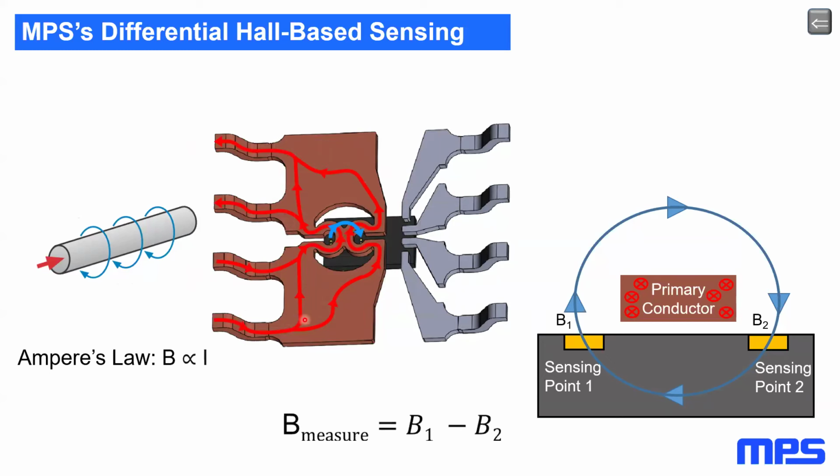And as this current flows through, we shape it through this very tiny, we try to get a really high current density right here. And you can see this current then is flowing in the up direction, which means we have a magnetic field curling around based on that right-hand rule. See these little yellow dots? These little yellow dots are Hall sensors. And these Hall sensors on the left side and the Hall sensors on the right side constitute a differential pair.